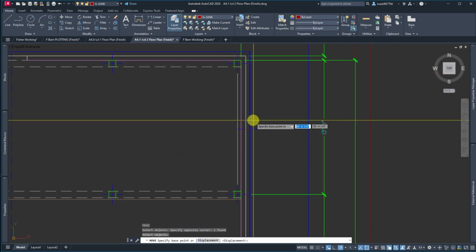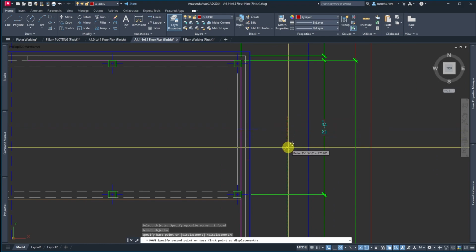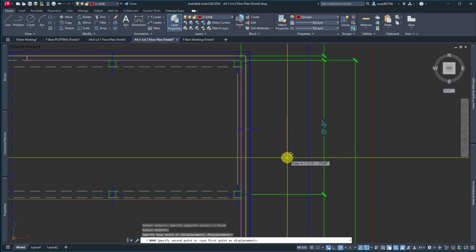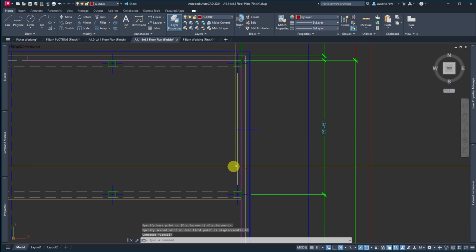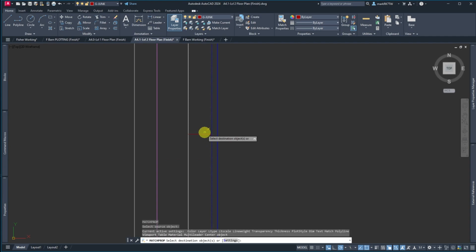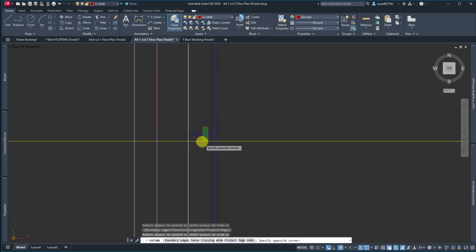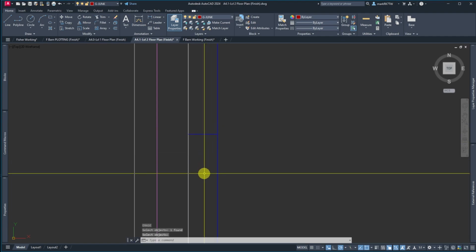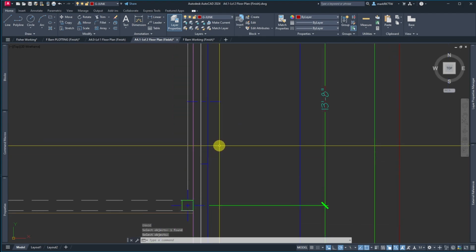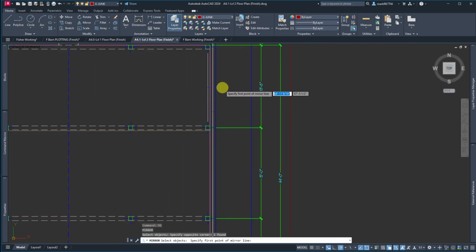And then let's come out and take a look, see what we like. So if I start pulling it down, I'm getting a readout number next to that word puller. And that's 3 feet. Now I'm at 4 feet. 4 feet's pretty good. So let's do 48. 48, enter. And then, so I've moved that. And then I want this to be on the same layer as this guy. So now I can extend it out to my siding. I could get rid of this. That was just a temporary line. Then I can mirror this about that center line.